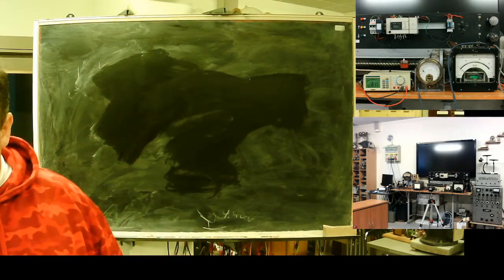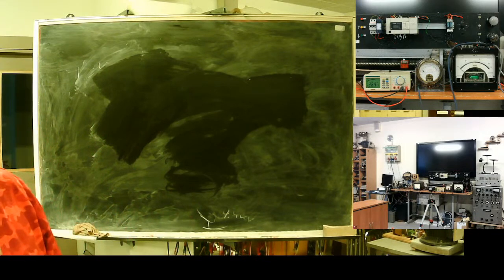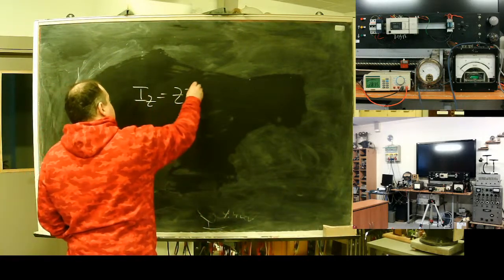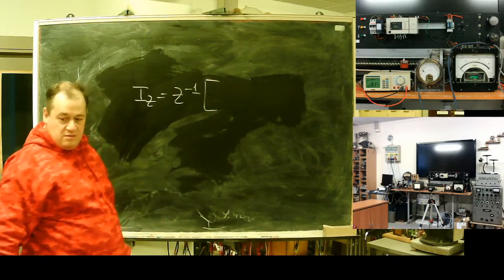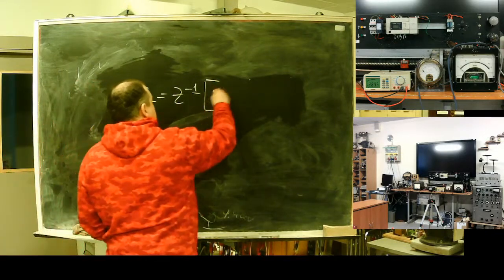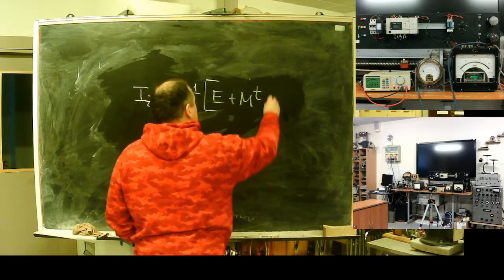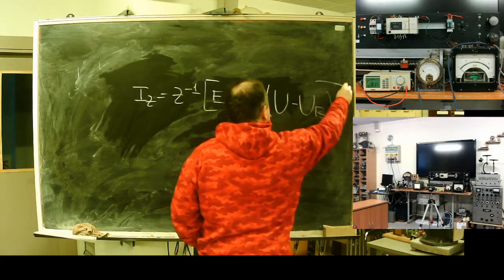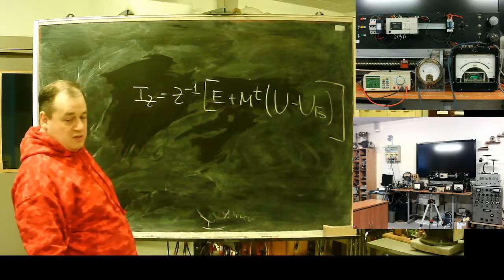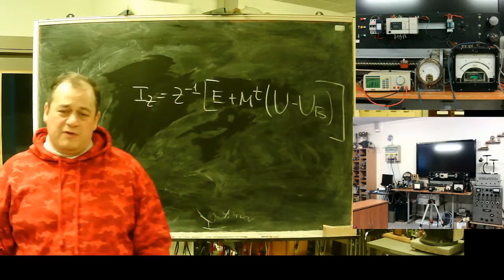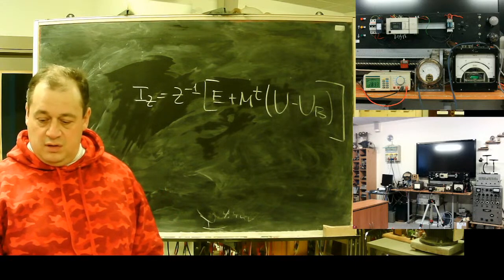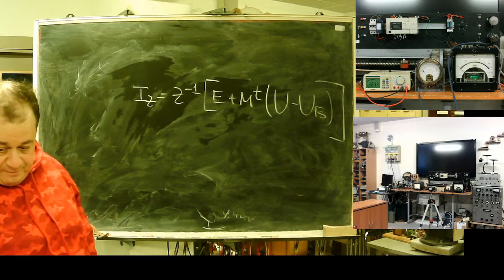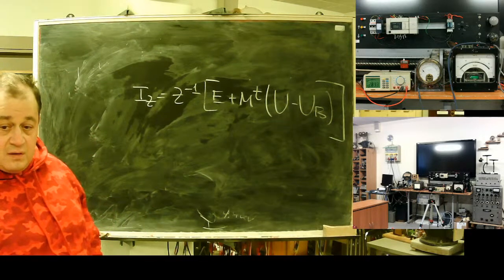You got voltages. Then the branch current vector? It's easy: M transpose times voltages plus base node voltage. Don't forget base node voltage. Usually we don't need currents or node voltage. In reality we need power flows.